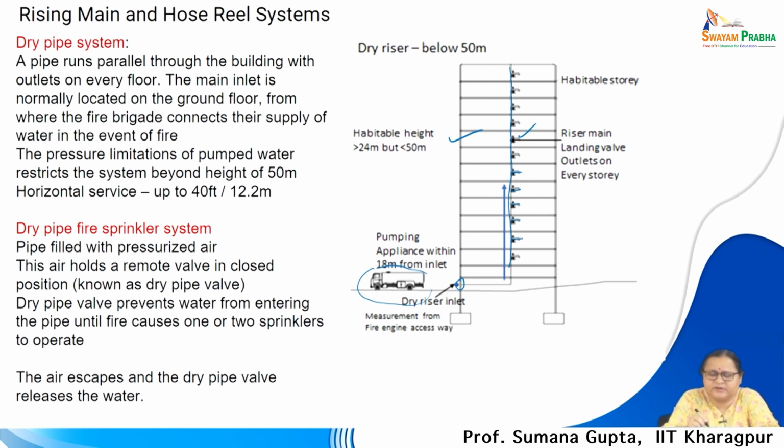What is important is the water pressure. The pump here takes the water under pressure to this point. Higher you go, the pressure drops, and there is a minimum. So, this water cannot maintain a high pressure at the upper points.